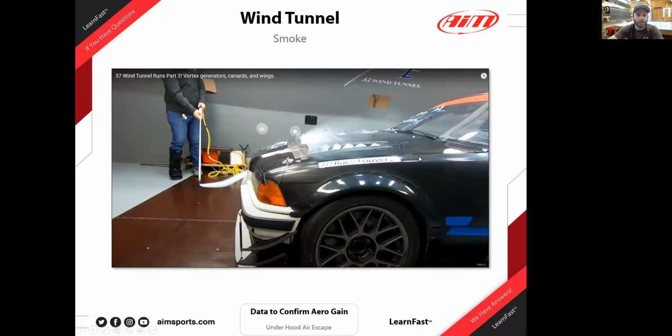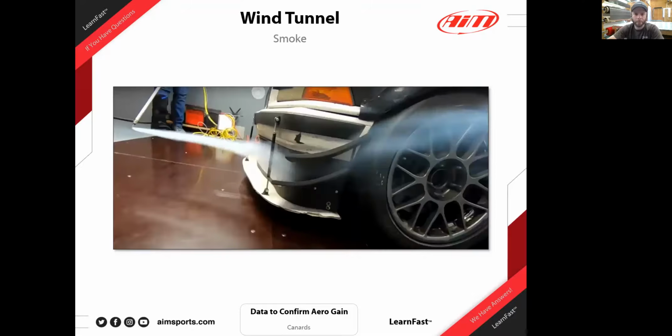It's one of those things where you don't want them too far rearward, for sure. And then too far forward, if the front louver is in front of your radiator, it's not really doing much either. There you go. So every car is going to be different: the front end style, how big the splitters are, how steep the windshield is, and where everything is placed. It is a science, but every car is different, right? So very good.